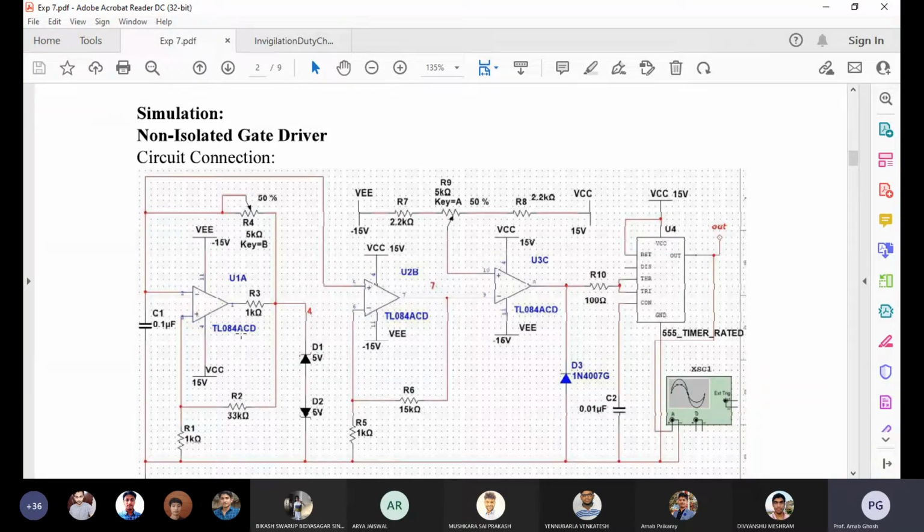Then how do we proceed if you are using a digital processor? First, analog to digital ADC converters are required before entering the computer. When you process all those signals and then want to send the signal from your computer to the physical system, you need to accommodate a digital to analog converter, a DAC. After the conversions, if you have a MOSFET, you can use a Schmitt trigger.